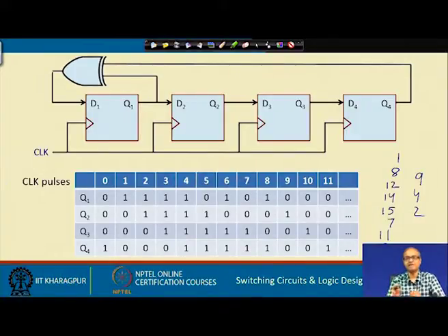There are some standard tests of randomness, and it can be shown that the patterns generated by this LFSR exhibit good randomness properties, with the exception of one test. Because the bits are shifted, the correlation between the bits generated in one stage and the next stage will be just shifted 1 bit in time. Other than that, all other randomness properties are very well satisfied.